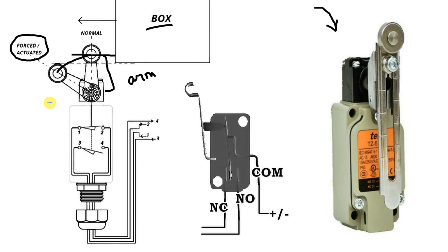But what exactly is this output signal? The limit switch is equipped with NO or NC contacts internally or in some cases externally. We provide power at one end of these contacts, and we receive this power from the other end in the form of a signal, right? Now, depending on the scenario, you should use NO technology or NC technology.